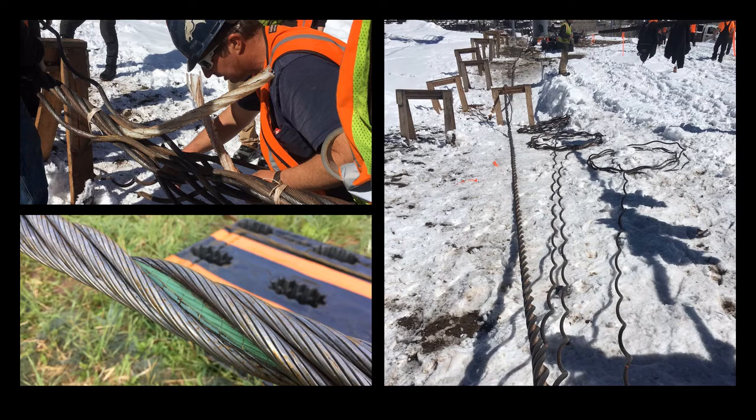The image on the top left shows the marriage, which is where the 2 ends of the wire rope meet. The strands that have been unwound are then laid on top of the opposite sections and then wound back in together to form the endless loop. The white segments of core are shown sticking out, forming that X shape from both ends of the wire rope.